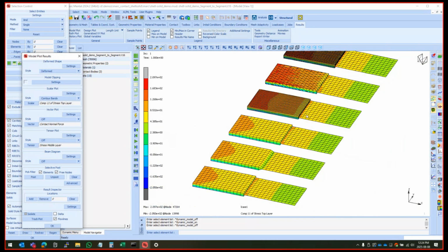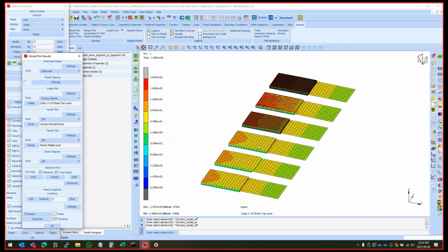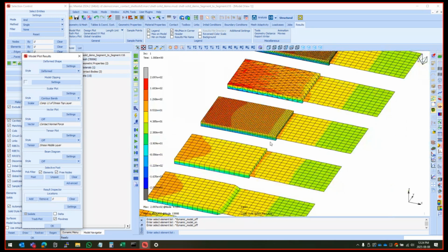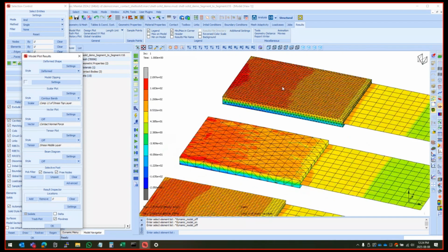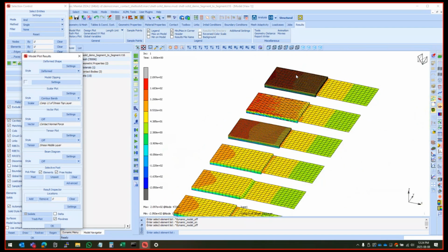I mean, is it easy to add a baseline model in here with just like 4 elements through thickness, all hex, first order? I don't have, as I say, I don't have one, but it's pretty easy to add. For that matter, I could have used shells and extended it. It's still within shell theory. Then I can also see how it behaves. Yep, but again, it's easy to add.